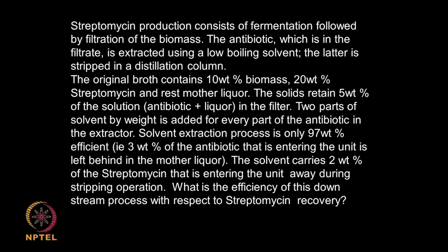Extraction is never 100%, even if it is 98%, some amount of streptomycin will go away with the parent liquid, it will not come into the solvent. Now, when we go to the distillation, your solvent may come at the top, streptomycin will come at the bottom, but some streptomycin may also go away with the solvent.